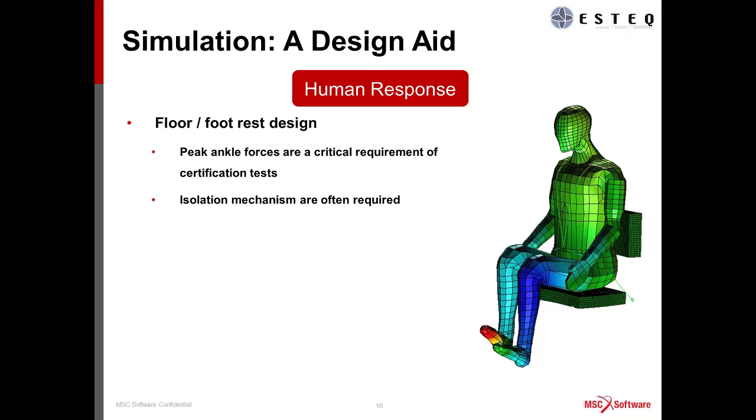So you've got to ensure that the ankle forces are kept below a certain value, and obviously the design of the floor and footrest are critical in that respect. Isolation mechanisms are also routinely employed to ensure that these peak forces do not exceed the specified values.